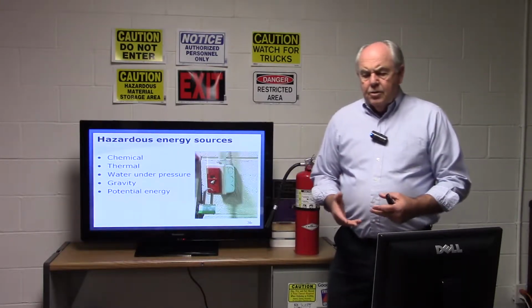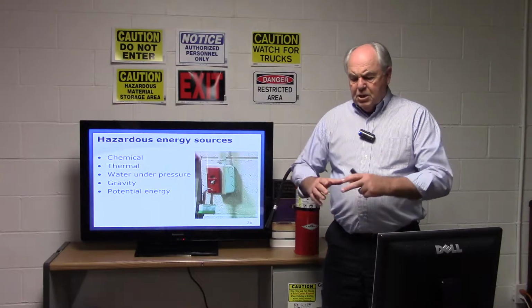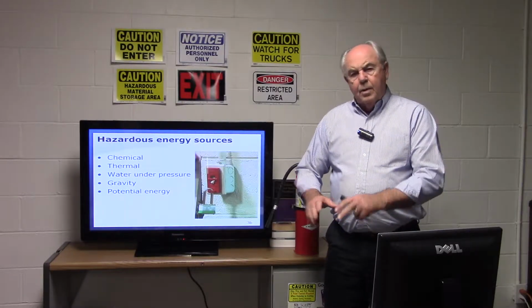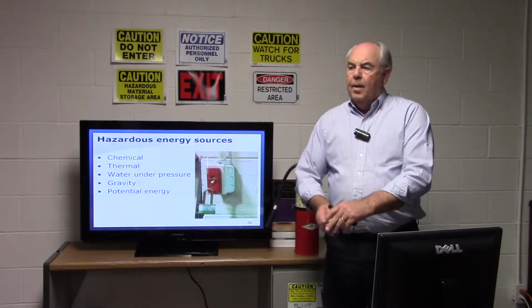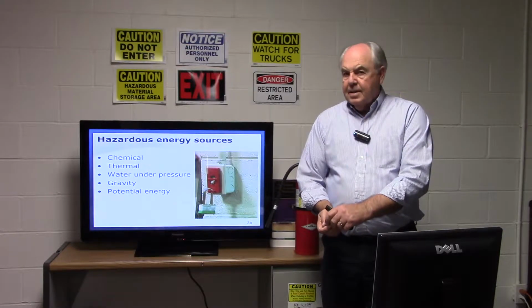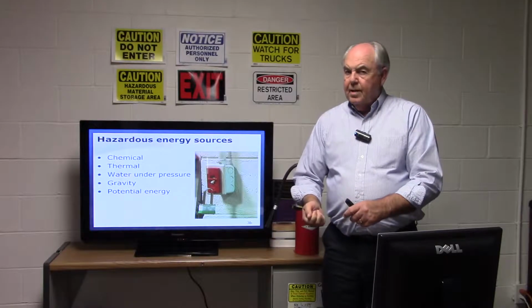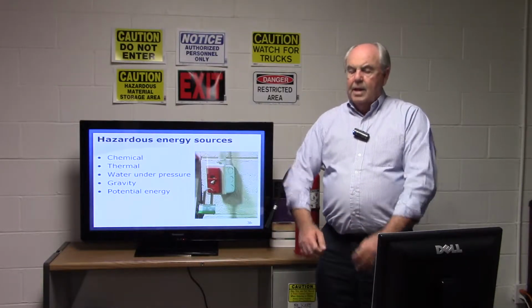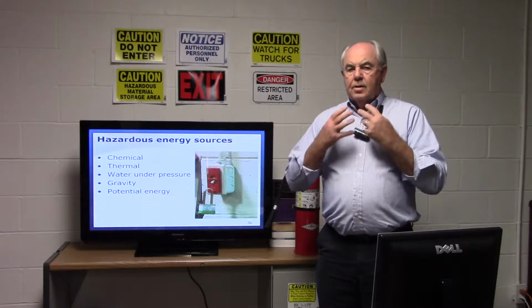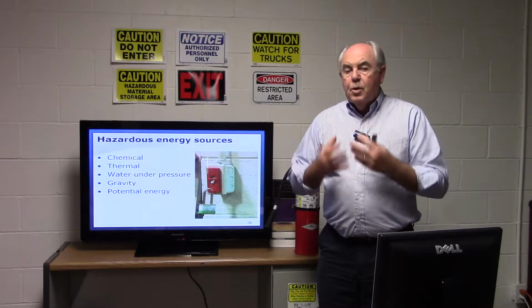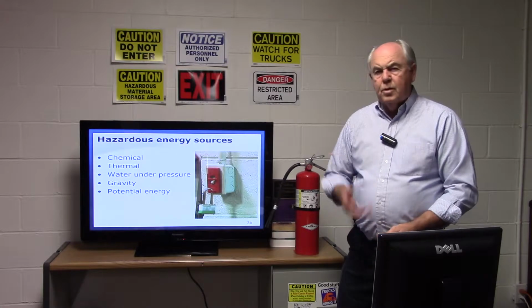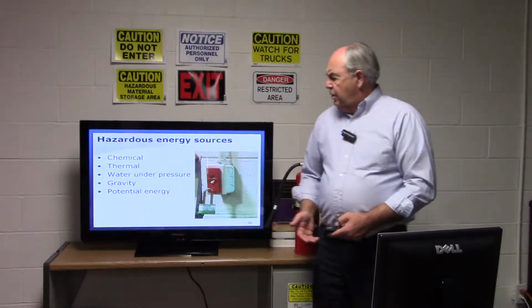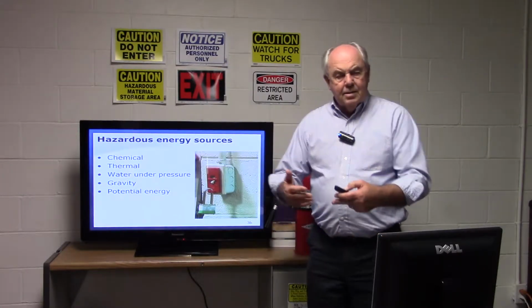Now, kinetic energy is, keep this in mind, you've got a spring up under a lid, and that lid is bolted down to hold that spring down. If you don't de-energize that spring, when you take the bolts out of that lid, what's going to happen? The energy of that spring is going to release, and you're going to find that plate or that door or whatever's holding that spring down is going to be all in your face, and you want to make sure that you de-energize the spring itself.